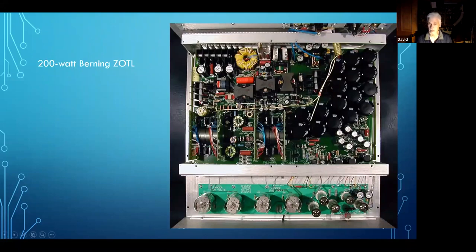Power supplies, I use parallel resonance, not pulse width modulated, but it also does incorporate power factor correction, which is a pulse modulated circuit that's up here. So it's a universal line voltage amplifier that draws its power in a sinusoidal waveform instead of high current spikes.